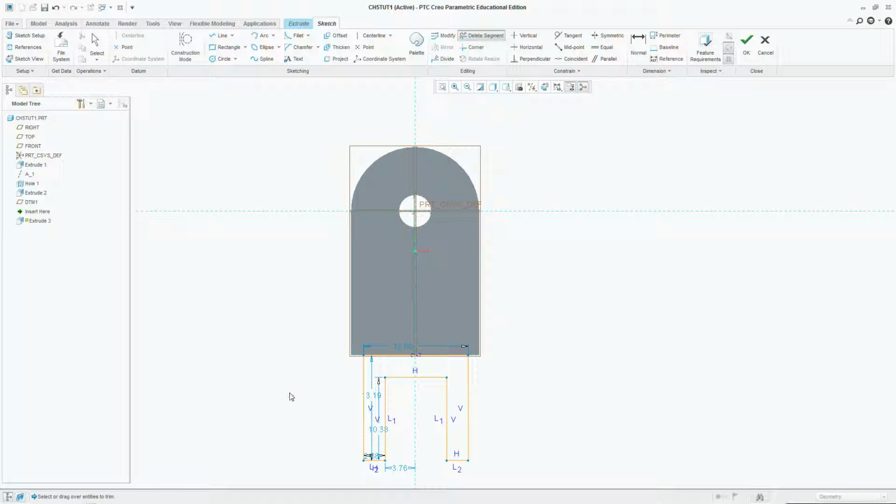This is still locked into where it's supposed to be. Now all I have to do is really dimension this. So I'm just going to go to normal dimensioning, and I'm going to put in my 25 for this piece, and I want this to be 2 from that edge. I want this to be 2 from this edge. And again, it's just middle click to place the dimensions once you get going.